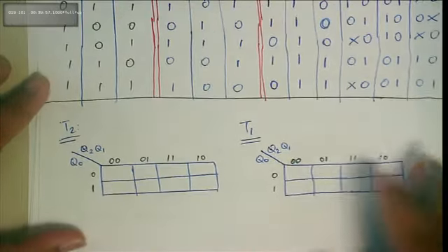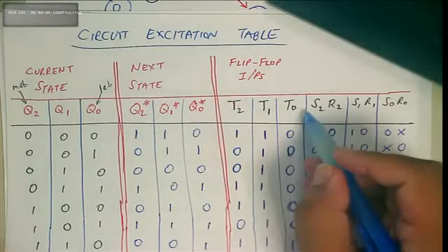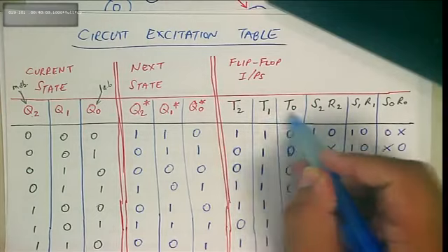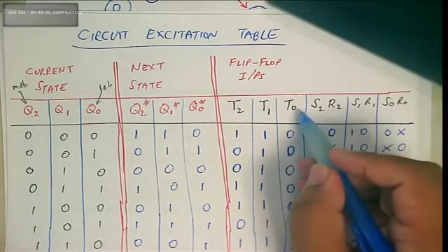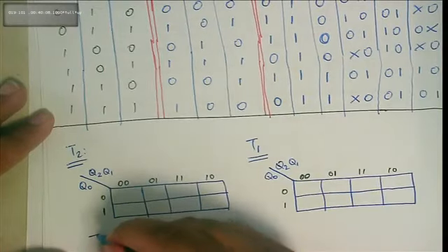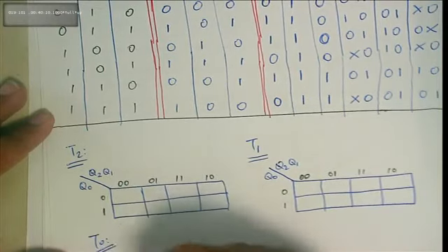all right, and you've got another third Karnaugh map. Remember, how do we know our Karnaugh maps? From here, from our design. The first problem said you design using T flip-flops, right? And our third Karnaugh map was T0.